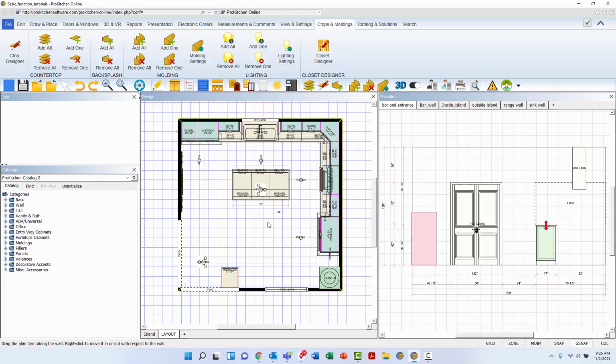The next option in the right-click toolbox is Move. This tool may also be used in either the plan or elevation view. When this is selected in the plan view, you will be able to move the countertop freely about the design. Once selected, the mouse will turn into a crosshair, denoting the Place and Edit mode. Left-click in the plan view anywhere and move your mouse about the design space. Then left-click again to secure the countertop into place.